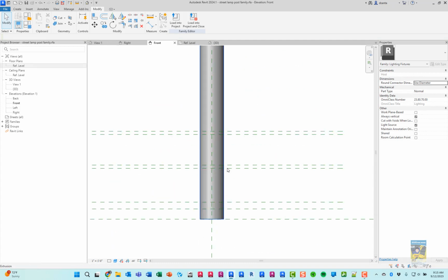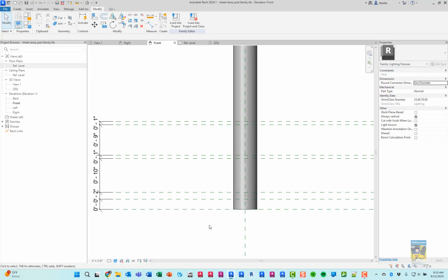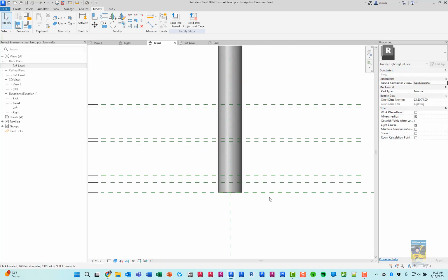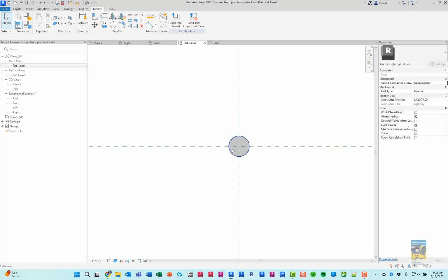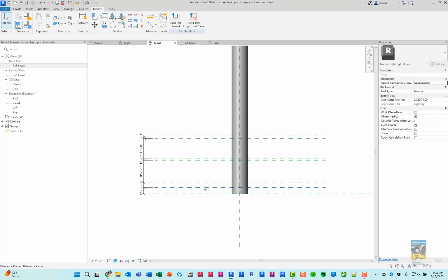Now, when it comes to this design over here, the base, let's deal with this lower plate and the second plate that's on top. That can be nothing more than, again, either an extrusion or a revolve. If I do say an extrusion, and we go to the reference plane, we can create that here and extrude it. But since we create a reference plane here, it gives us that sense of vertical height. It doesn't give us diameter in the sense of the size.